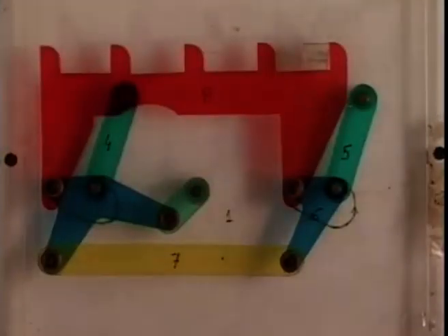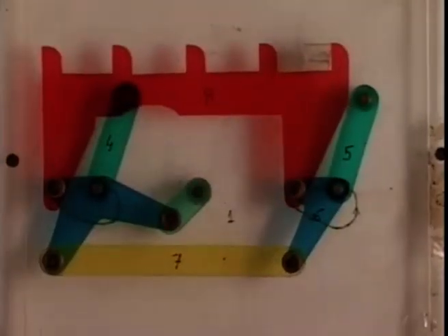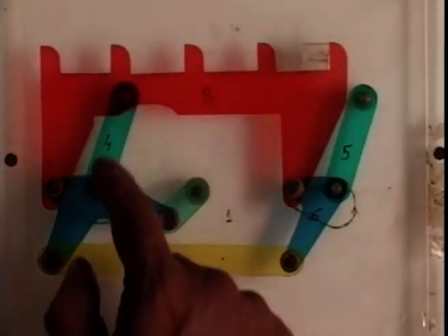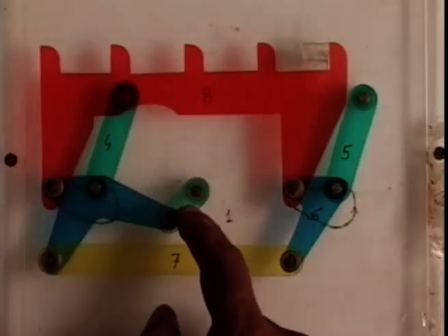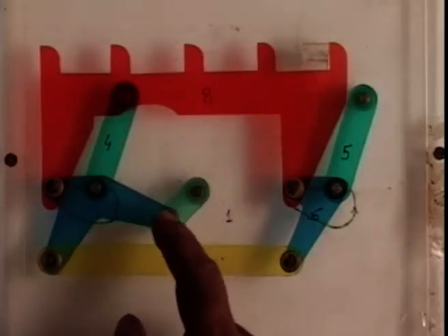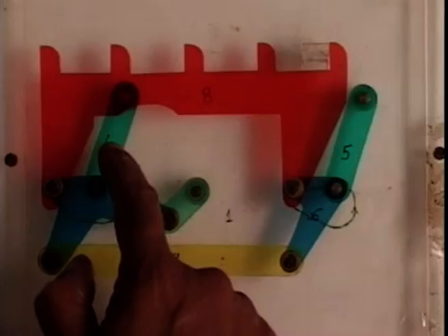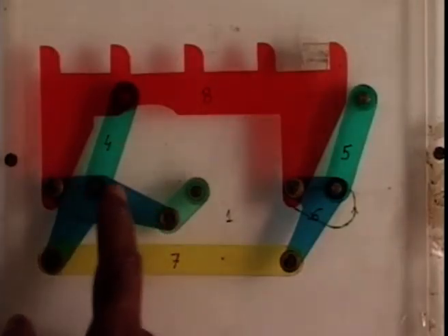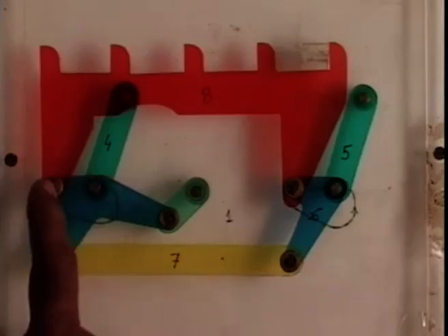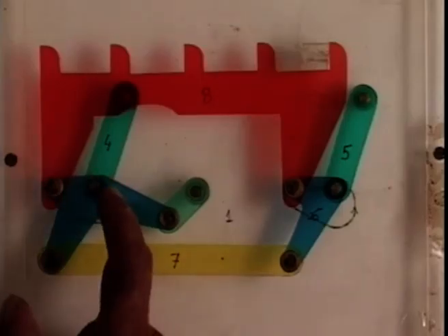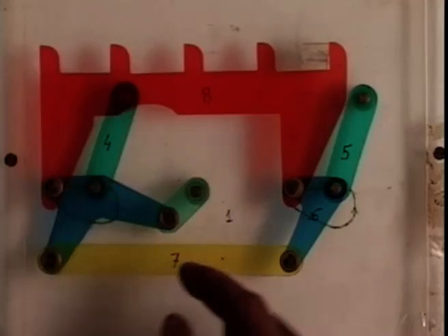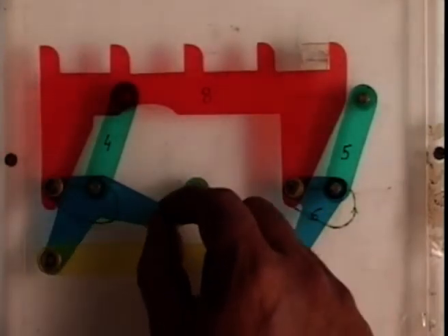As a last example of path generation problem, let us look at this model of an 8-link transporter mechanism. Here we have a 4-link mechanism. Link 2, that is the crank, which is the driver, this is the coupler, and this is link number 4. And in this coupler, this particular point, we want to generate a curve which has a vertical portion, has a horizontal portion, and comes down. Now you see, if we drive this